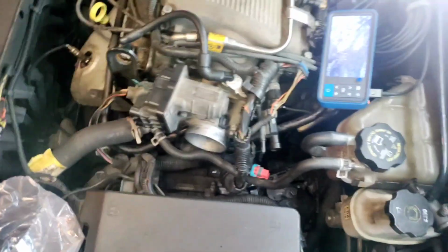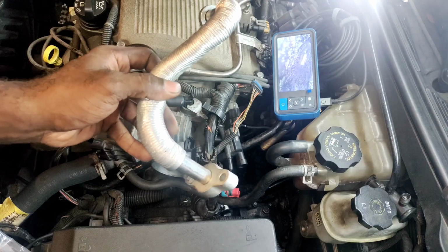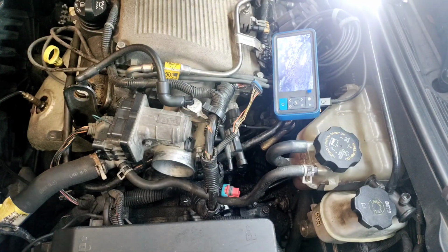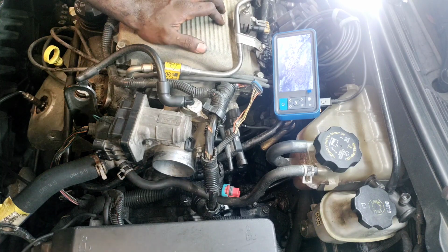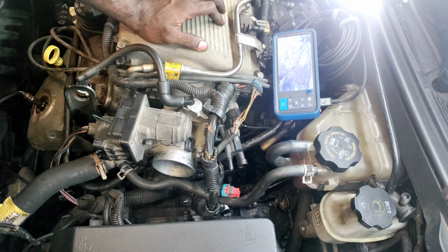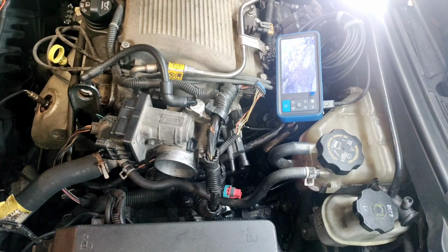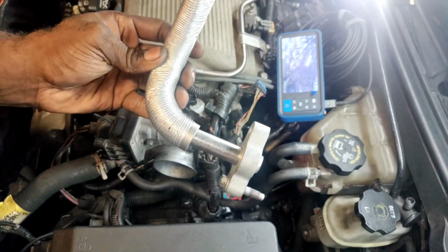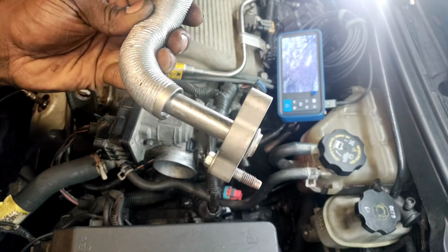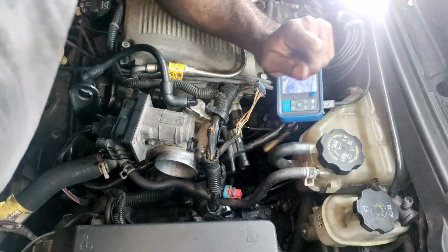Let me let the customer know what we're dealing with. Man, I tell you what, the customer bought their own parts, and the EGR tube looks like crap. I told him, just let me know everything you bought. They just said, oh, I just got an EGR valve and the harness. That's the EGR tube too. And then he started working on it, and there was a gasket on there. This has got to be Amazon quality, because the flange doesn't look nowhere near as thick on the factory one as it does on the aftermarket one.